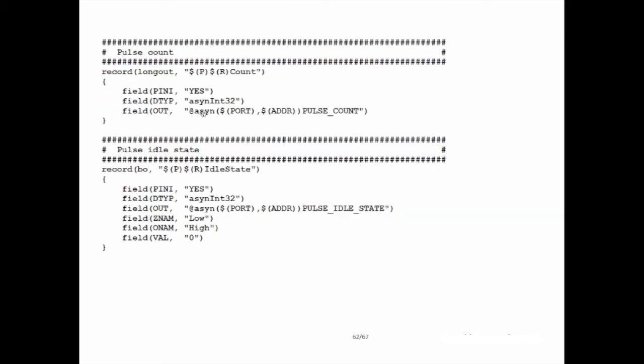The driver doesn't have to worry about both. The driver only knows about period, but if you change the frequency here, it'll calculate the period, and if you set the period, it'll calculate the frequency, because sometimes users like to see both. Similarly, the width is implemented directly, float 64. A delay, again, implemented directly, float 64.